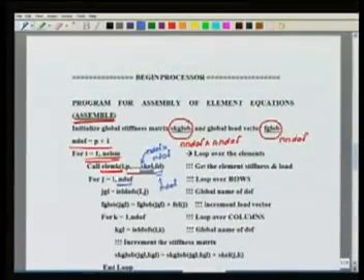So for that we start looping over the degrees of freedom for the element, that is, we loop over j equal to 1 to ndof. For each of these degrees of freedom I get its global name. So for the element i, take the local j, and from what we had done in the previous routine, we are able to find the global name of this degree of freedom. We call it JGL, that is, j global.